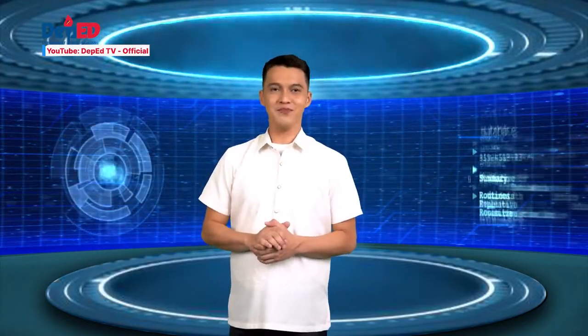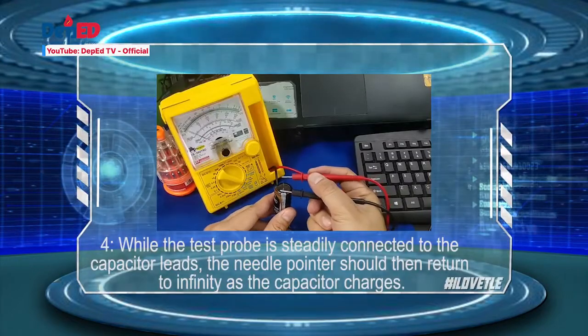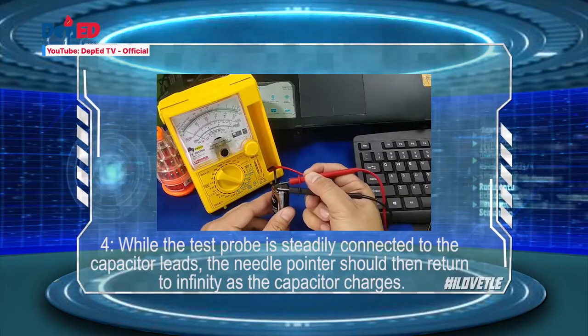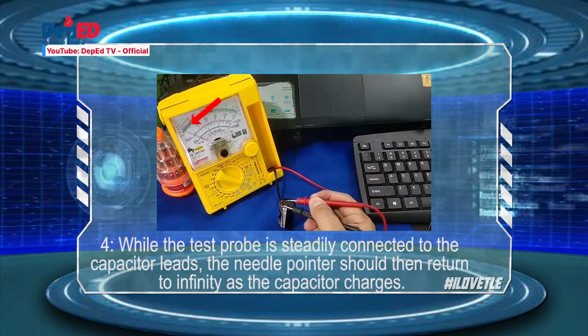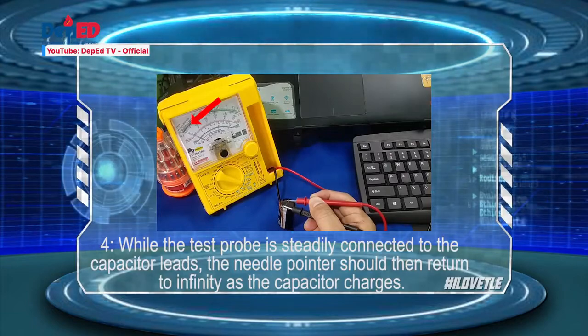Amazing! You have just learned how to check a working capacitor. Step 4. While the test probe is steadily connected to the capacitor leads, the needle pointer should then return to infinity as the capacitor charges.